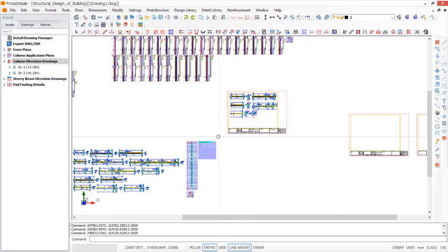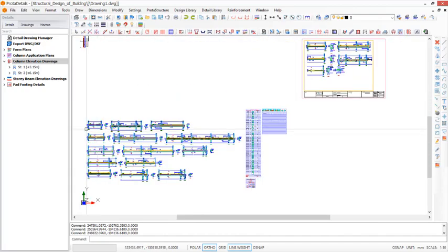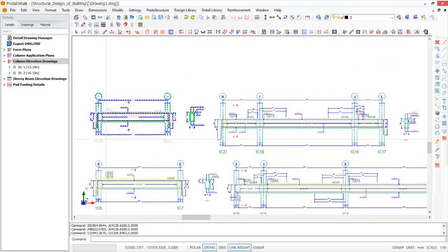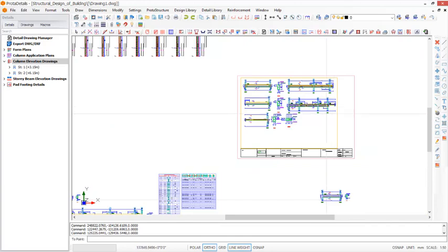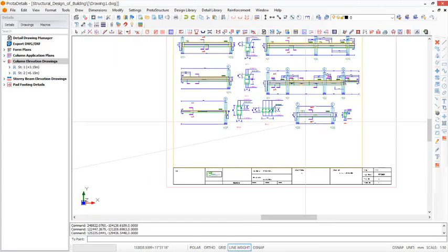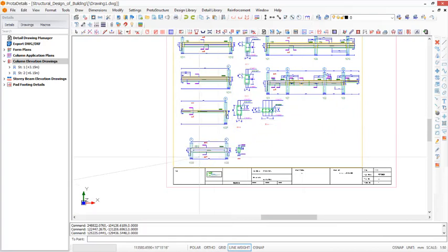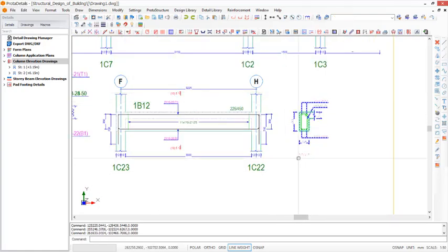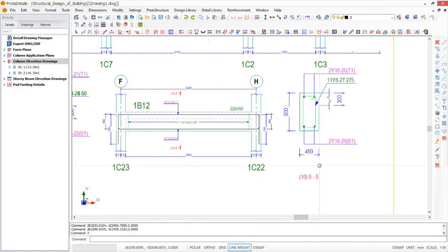Okay, you can proceed to place another drawing. So you can look for a drawing that is not too much in the length, or in span, like this one. You can just place this right here, or you can have it placed right here, whichever provisions here. Okay, it's placed right there, and then you can always scale this to 1:50 right here, 2, and enter, just like this.